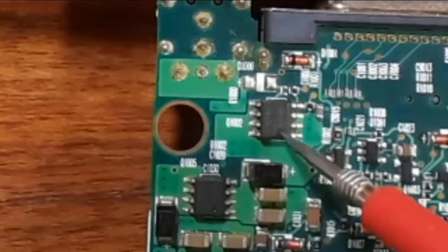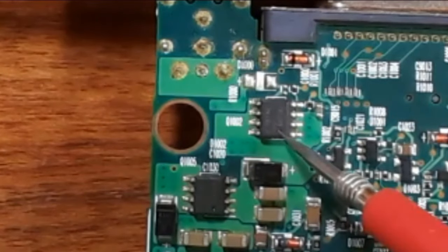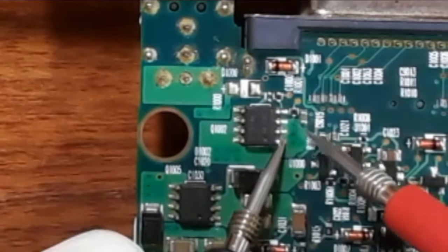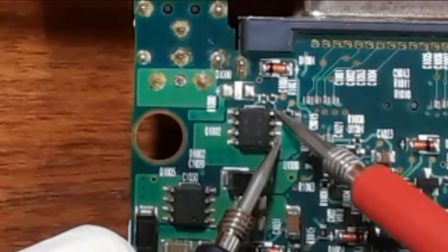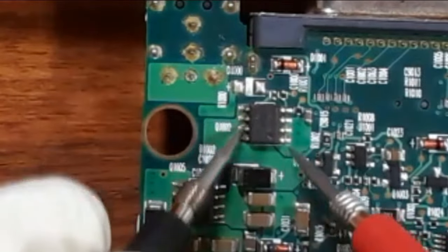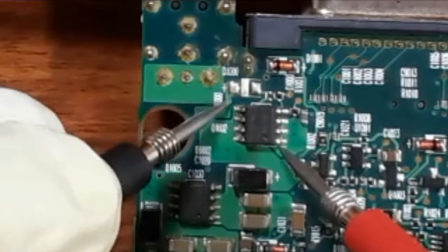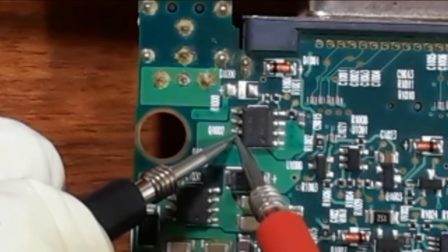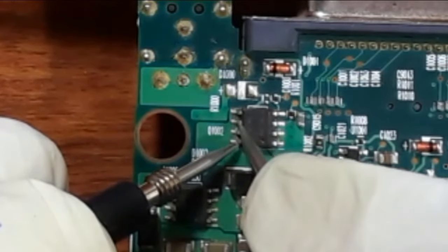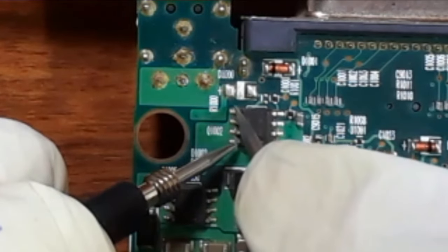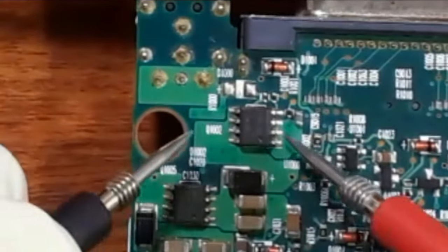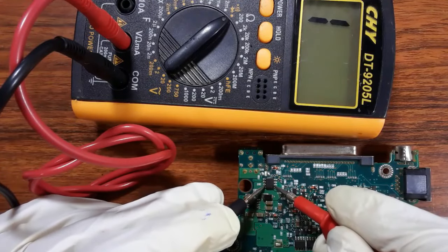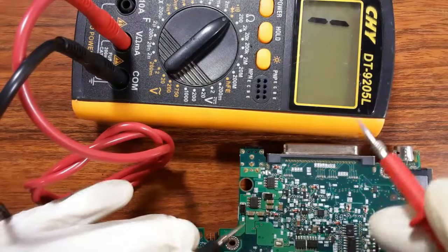We can check it. Here we have this point over here. As you see, this is source. These 3 are source, and here we have the drain. And of course here we have source, then here this is drain. Let's check this. 4 should be connected together. Let's check. You see all these pins are connected together. So let's check between source and drain. No continuity, as you see, means this is a good MOSFET.